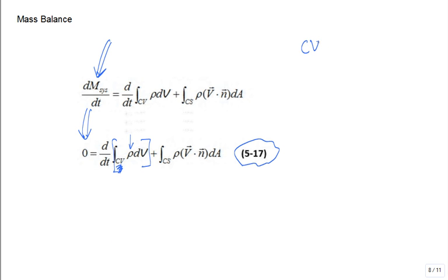The control volume can be fixed in space, or it can be a deforming control volume. I think the math is rigorous enough, so let's just have a fixed control volume in space. Don't do a deforming control volume. Just a fixed control volume. So basically, is it piling up and are you getting a higher density, or is the density changing? That would be changing the mass in the system.